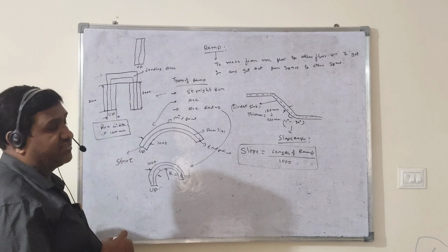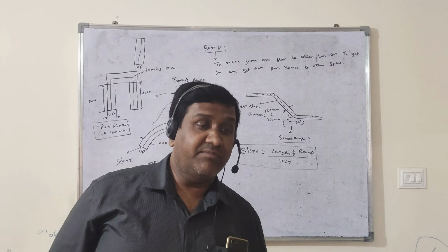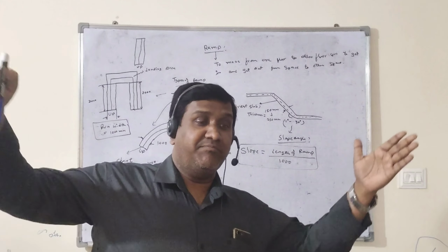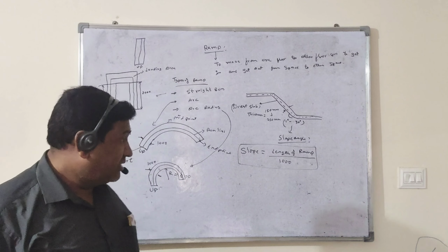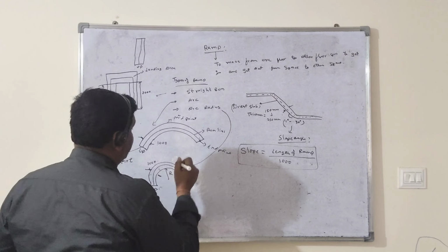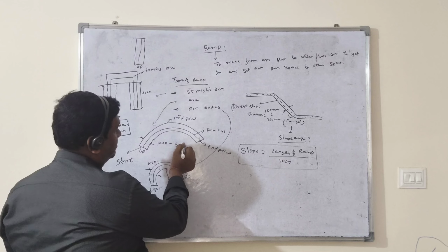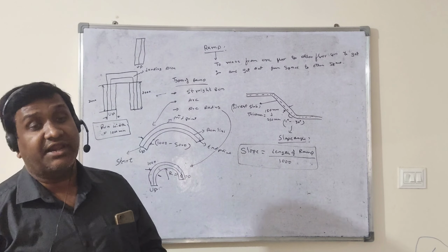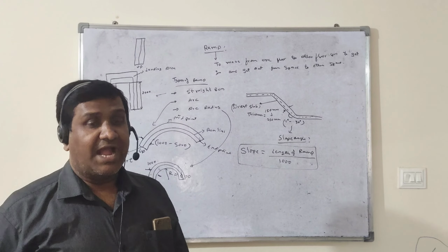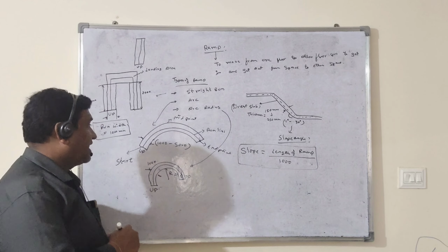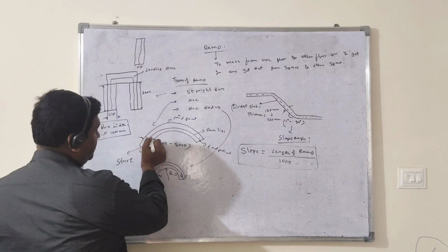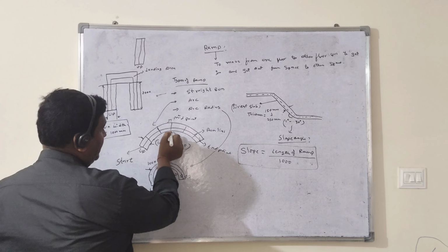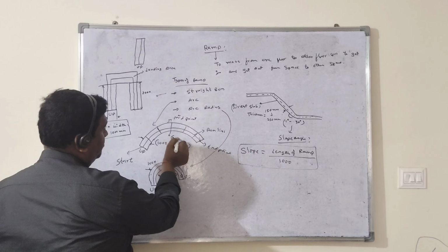So wherever you are going to design any ramp, the run width will be minimum 1000. But for the parking area, you can see there is a big space there. So minimum 1000 and maximum you can take 5000. So minimum 1000 to 5000 you can take as the run width of the ramp. And on every ramp you can see they put some grooves. On every ramp there will be some lining, and that lining we will call a groove.